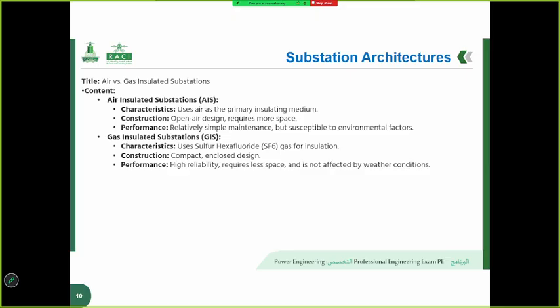Okay, this slide focuses on two primary architectures for electrical substations: air insulated substations, or AIS, and gas insulated substations, GIS. The choice between these two designs is a critical decision in power system engineering, influenced by factors such as available space, environmental conditions, and cost.